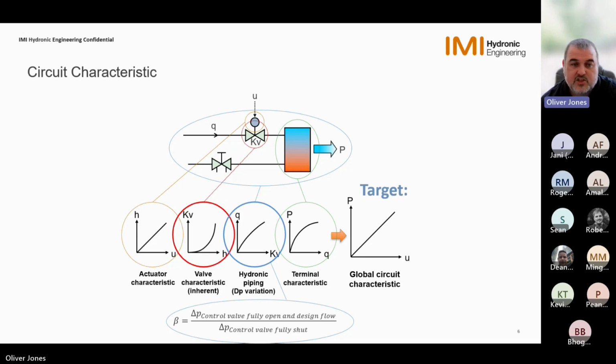Typically, we tend to see this type of curve on heat output coils for fan coils, for air handling units, very generic terminal units throughout our systems. Our valve characteristic, in our TA-Modulator's case, slightly different. But we're looking at an equal percentage characteristic, which is almost the mirror of our heat output coil curve.